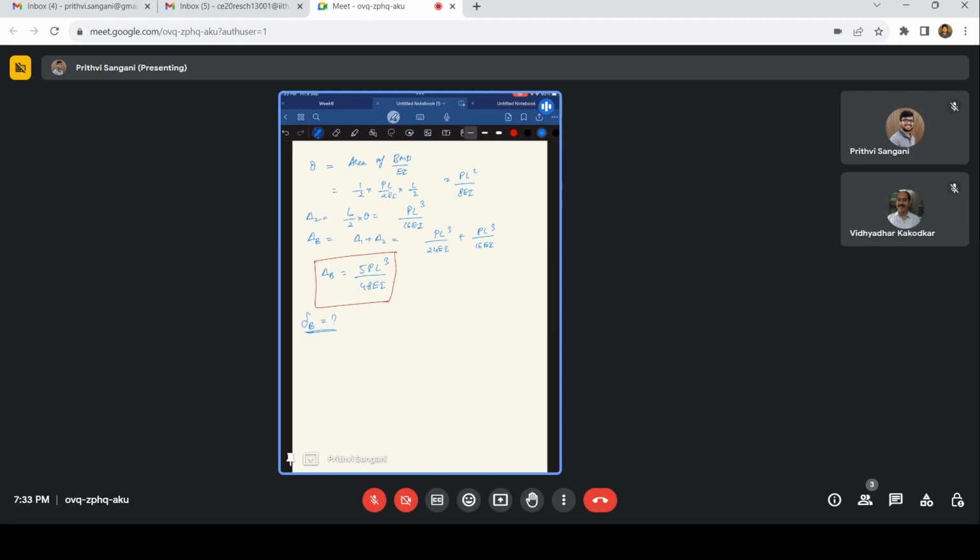Okay. So the actual unknowns are only 6 internally. I'm talking about the internal unknowns. So you have 6. So internal indeterminacy, DSI, usually we call it DSI, is 6 minus 3, that is 3. So internal indeterminacy is 3 in this case. For this you need to have the external indeterminacy is 6. Okay, the internal indeterminacy is 3. So you need to have 9 redundant forces to actually find out such a kind of a problem.